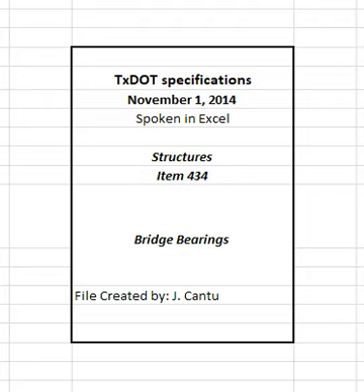2.3.3 Elements of HLMR bearings. 2.3.3.1 Lower component. 2.3.3.1.1 Polyether urethane for disc bearings. Furnish polyether urethane discs conforming to the material requirements of the TxDOT LRFD bridge design specifications and TxDOT LRFD bridge construction specifications, and the load and rotation demand indicated in section 434.2.3.1, Structural design.